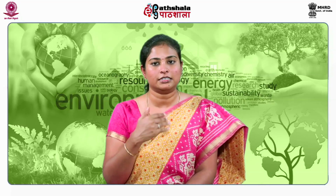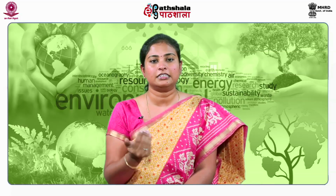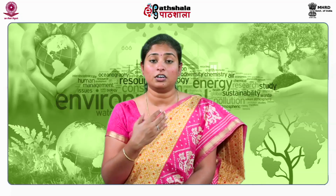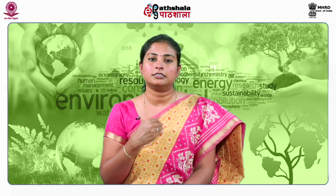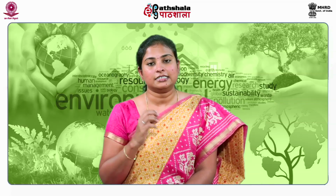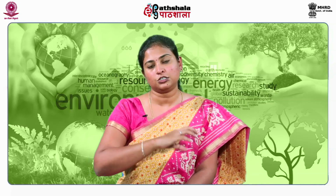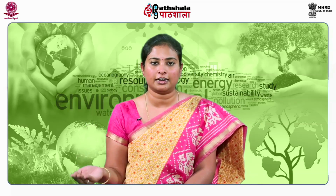You have to measure the cellulose and lignin level in the bioreactor, which will help in determining the phase of biological activity. Then the leachate yield and quality will again tell you the rate of degradation occurring inside the landfill bioreactor. Short circuits in the leachate system can also be determined. Then by characterizing the leachate, you can analyze what phase is occurring inside the landfill bioreactor. Like the acetogenic leachate will have a different characteristic and the methanogenic leachate will have a different characteristic.